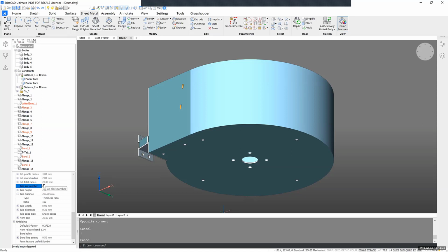I hard-coded this value 2, so this will take priority, and the tab distance will not be symmetrical. I think it will create 2 tabs indeed, but it will just start from one edge. That's, I think, what will happen. If you don't want this and you just want as many tabs as possible with spacing of 200 millimeters from each other, then you can put this on 0, and it will do an automatic, every 200 millimeters I want a tab, and it should nicely go around the entire edge. Then this is what we need.